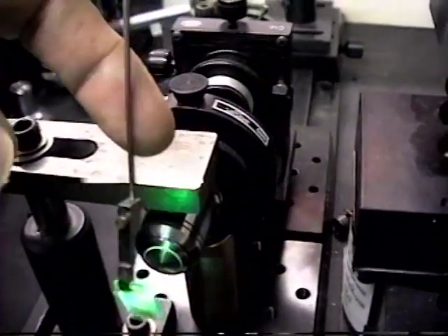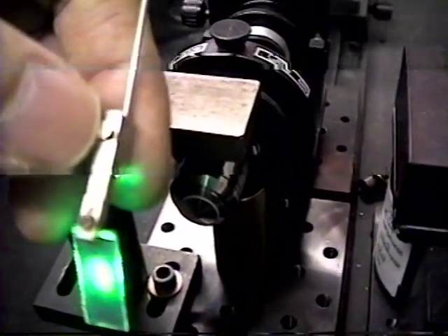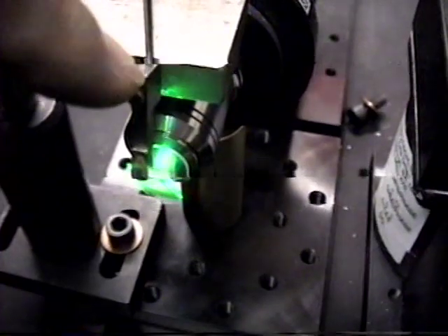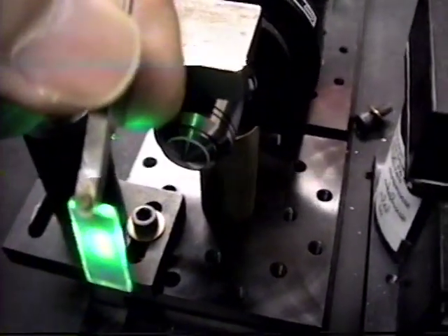Another thing I did was I remounted the tip of the fiber. There are actually 2 diameters of shaft here on this tip, and the screw is still firmly clamping against the smaller shaft diameter. However, now I have the larger shaft diameter protruding into this hole here of this larger piece of metal, so that the big shaft goes up, just missing the screw, and then the screw screws into the little shaft, and that way they both get bound together.